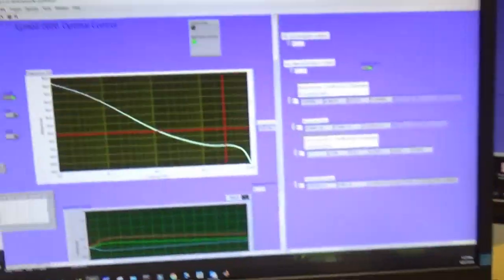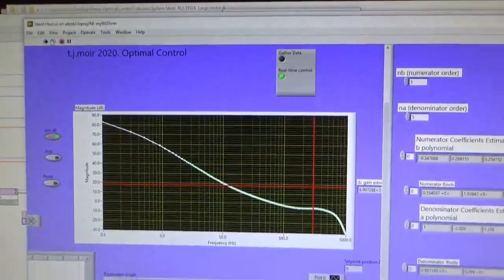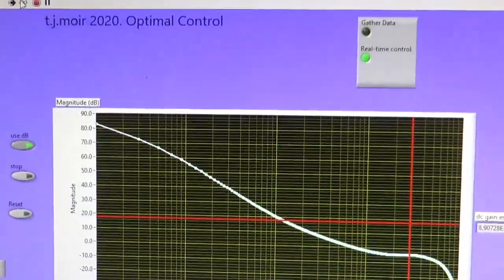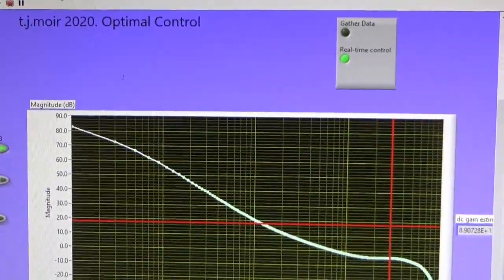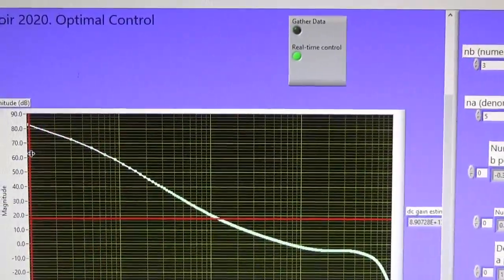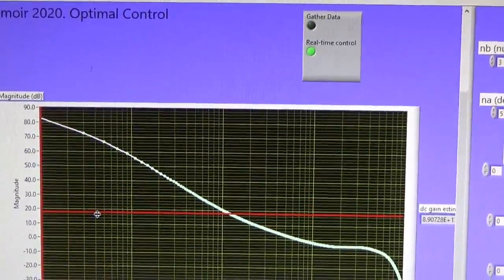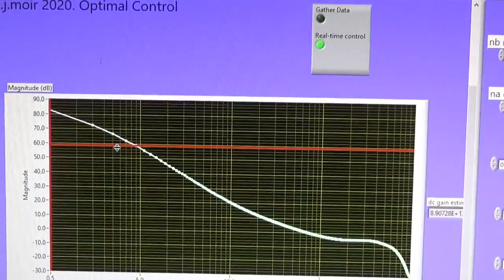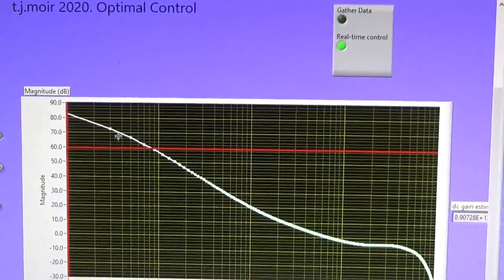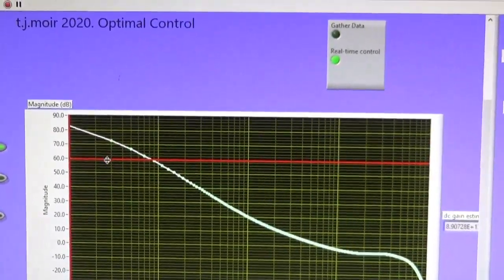And if we go back to here, you'll see there's the Bode plot. Just to make sure this does make some kind of sense, this should have a slope. This is our first integrator. That's got a slope of about 20 dB per decade, if we look at it roughly.